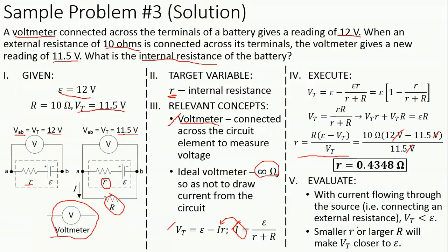And if you want the terminal voltage to be close to the value of the EMF, then we reduce the size of the internal resistance. How do we do that? Either we choose a different type of battery or we connect different cells in parallel, with the latter case being the topic of lecture 5.